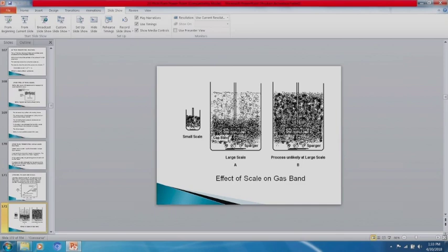Anyway, small scale, they had the behavior where the gas went throughout the entire reactor or fermenter very well, and they thought that on the large scale you would have this happening. Unfortunately, you have around the impeller a gas band formed, and the rest of the reactor or fermenter was a bubble column. Around here, there would be 50% gas. Here, down at the bottom, there would be 0% gas, and up here, bubble columns are typically 15% gas. So the reactor was essentially the 50% gas.